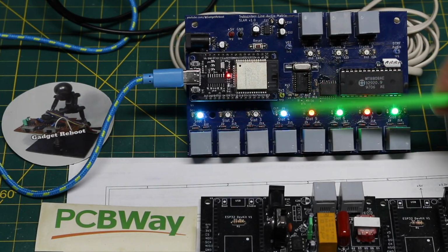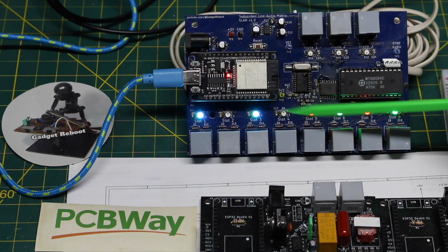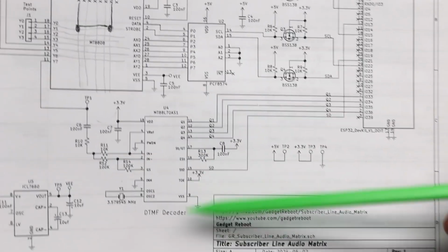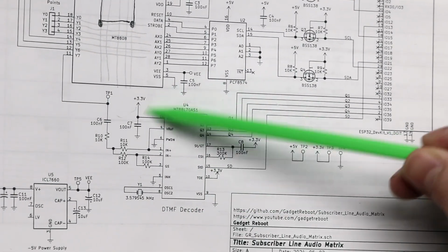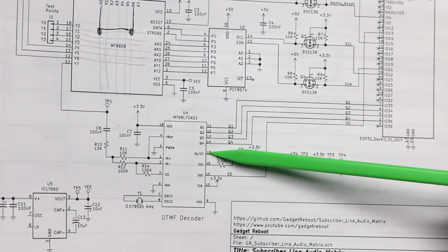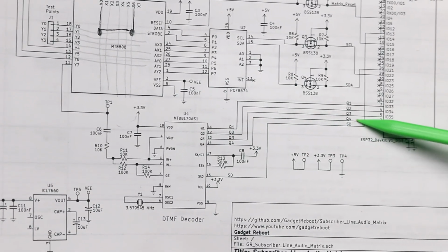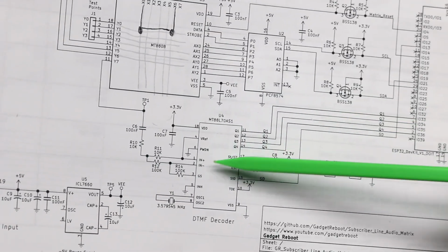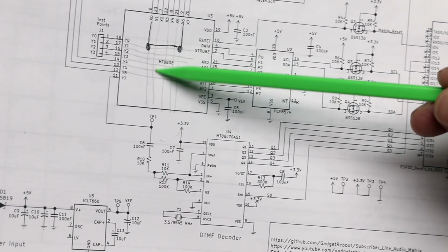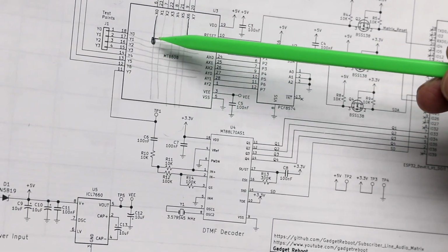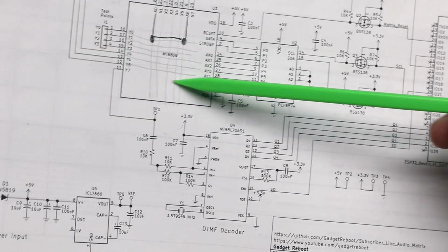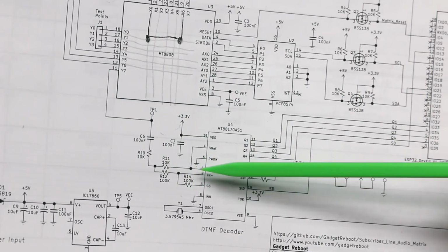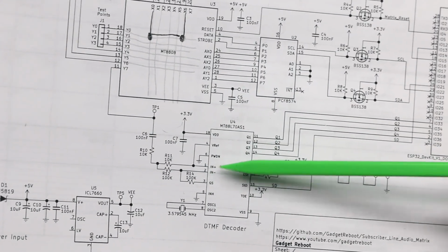So now we can look closer at the schematic for an idea of the circuitry, and I'll look at the schematic more as a block diagram. So here's the DTMF decoder. It's a standard circuit we've used before. So it has the digital data representing touch tones being pressed going to the ESP32, but I'm not using this right now. It's just in this analog matrix where I can connect signals down onto this line here and send audio into the DTMF decoder when I want to detect touch tones. So we don't really need to do much with this right now.